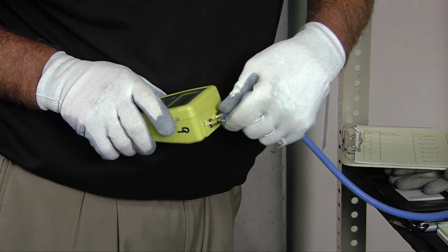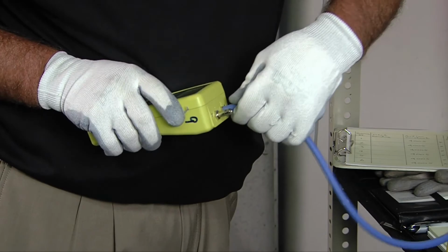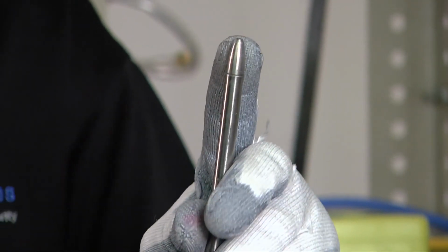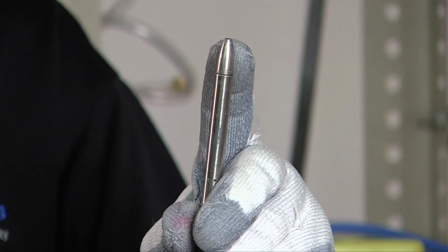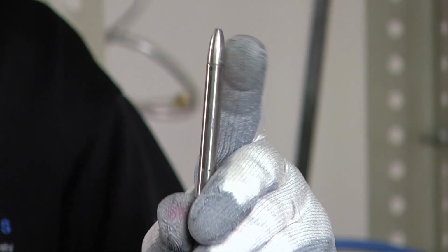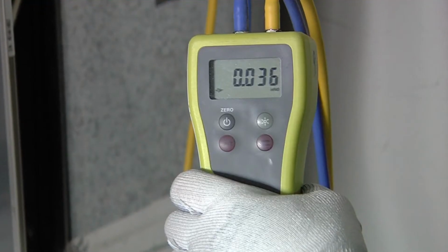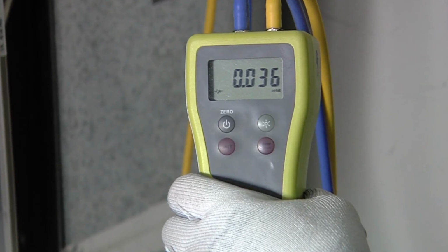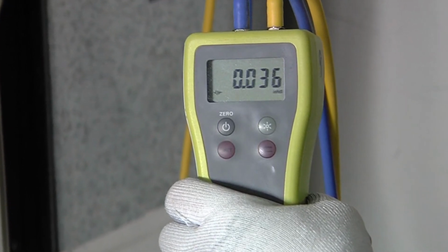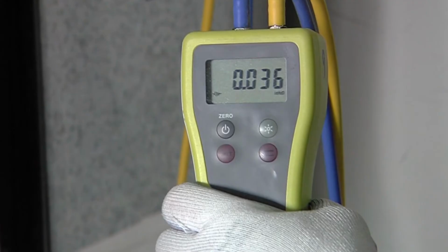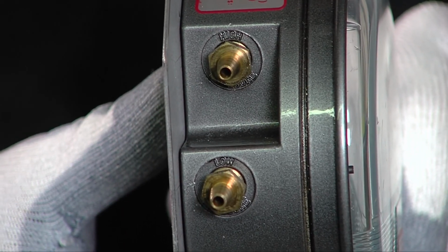Connect the pitot tube to your manometer or magnehelic. There are 2 sets of holes on the end of the pitot tube, a total pressure hole at the tip of the probe, and 8 holes for static pressure. When connected as shown, the reading on your manometer will be the velocity pressure. Note that if you're using a magnehelic, it will have high and low ports.